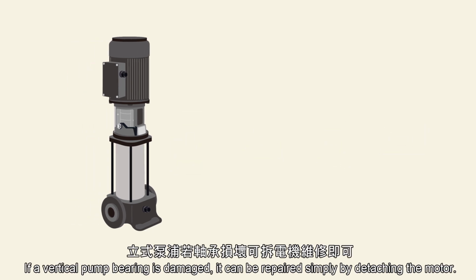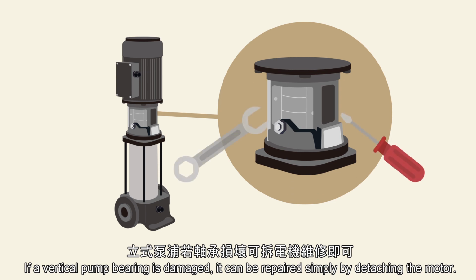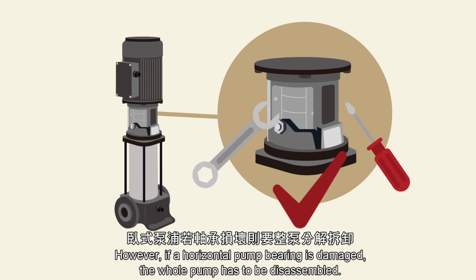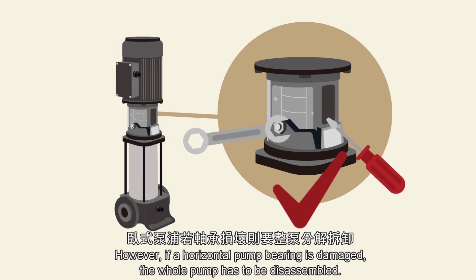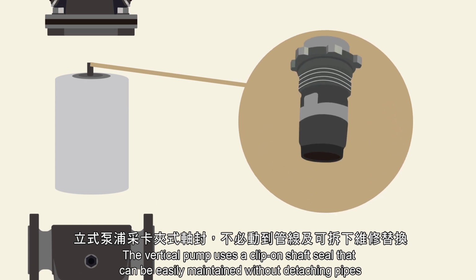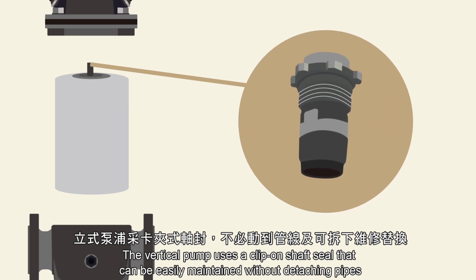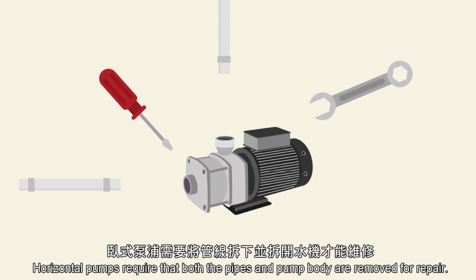If a vertical pump bearing is damaged, it can be repaired simply by detaching the motor. However, if a horizontal pump bearing is damaged, the whole pump has to be disassembled. The vertical pump uses a clip-on shaft seal that can be easily maintained without detaching pipes. Horizontal pumps require that both the pipes and pump body are removed for repair.